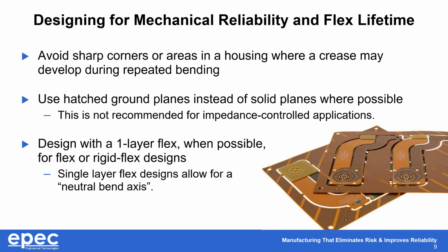And then, once more on the design side, you want to use hatched ground planes instead of solid planes where possible. This is more key for dynamic applications due to the higher strictness of the bend radius.